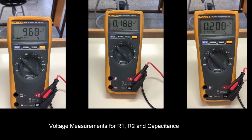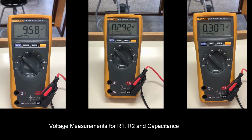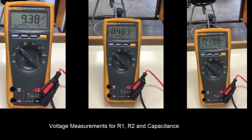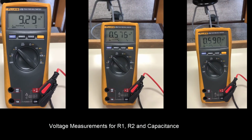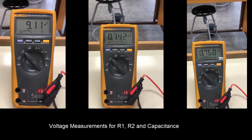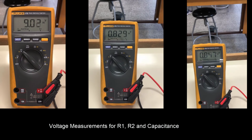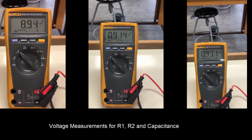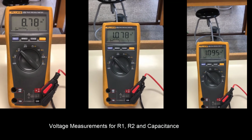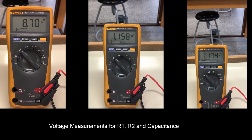Secondly, the loop rule will be tested with a multimeter setup similar to part B, measuring the potential difference over circuit elements. Voltage values are noted at 5-second intervals for 30 seconds. Data is displayed on table 8 and graph 2. Comparison of the theory and experimental results is calculated every 5 seconds. And in the end, a mean error value is found, which is noted in table 8.